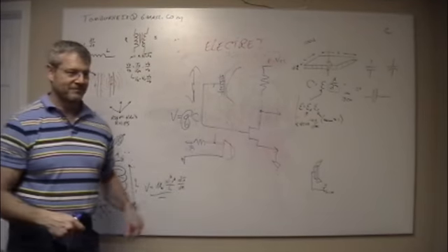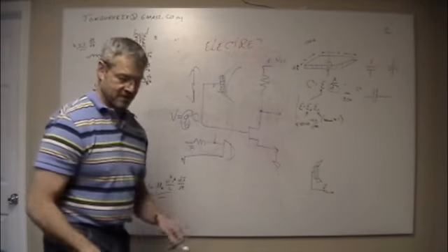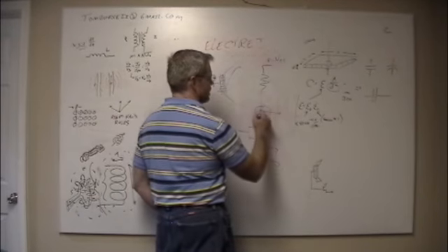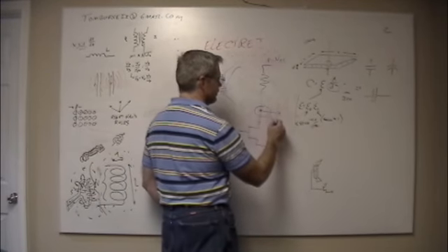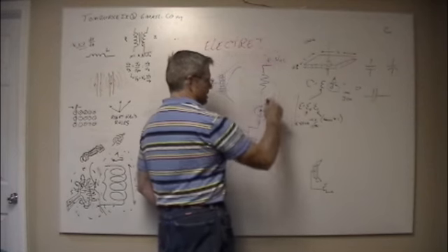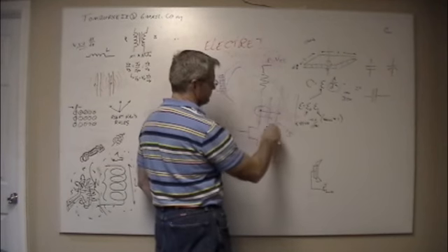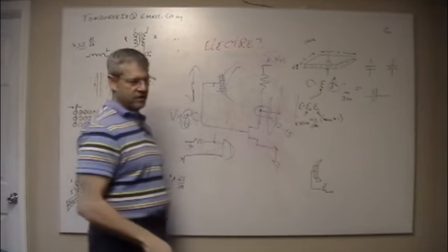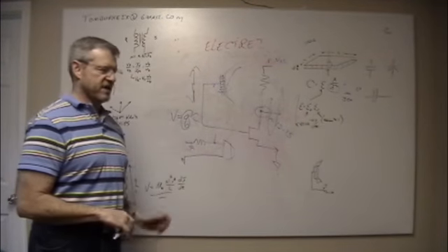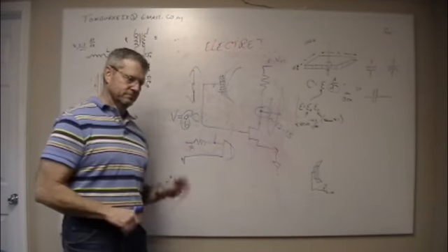Electret microphone. They generally, if you put 5 volts on them, this voltage right here, if I remember right, is about 1.2 to 1.5 volts. And you'll never see a signal bigger than about a volt off of it. And it has absolutely no current. So you have to have a high impedance amplifier on the other end to convert that.